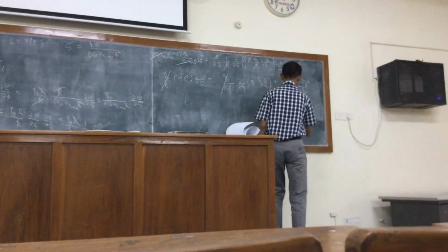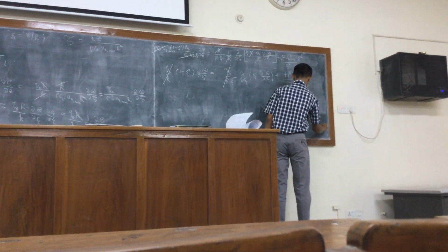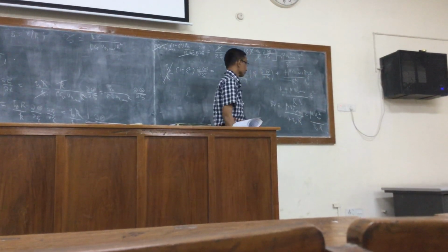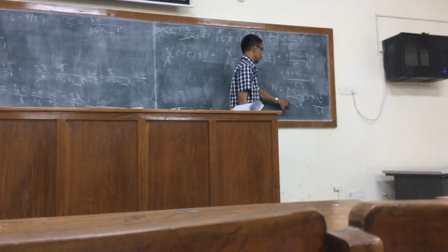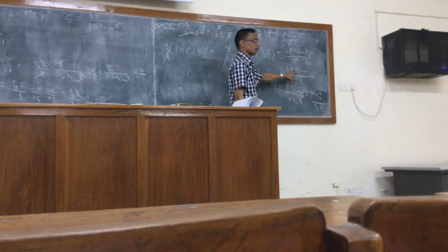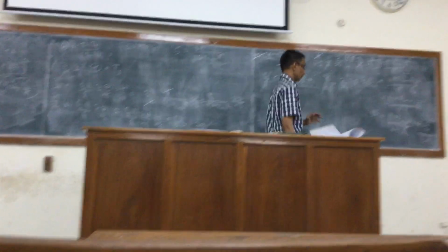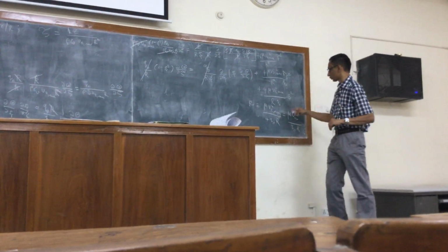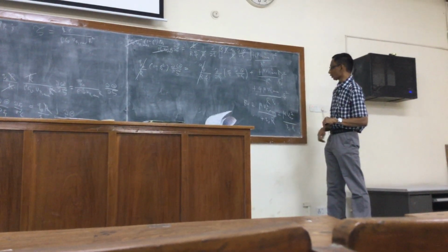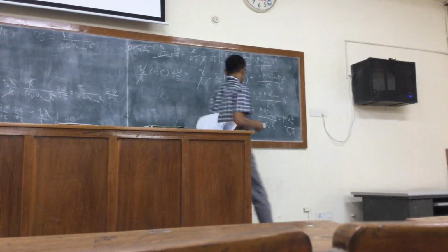So this is actually the average velocity squared by q naught r. So that is how it is defined. Since the 4 is taken care of here, because V average is dz max by 2, the average velocity. So typically a parabolic profile that you are very much aware of. So this can then be written with this definition of the Brinkman number.